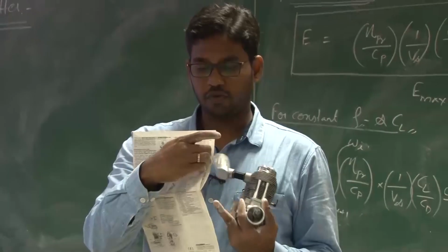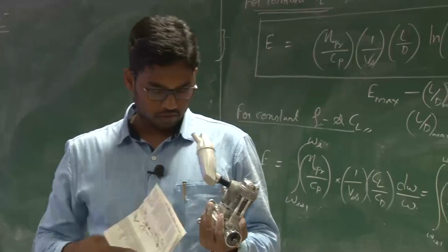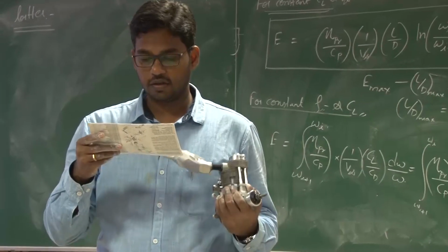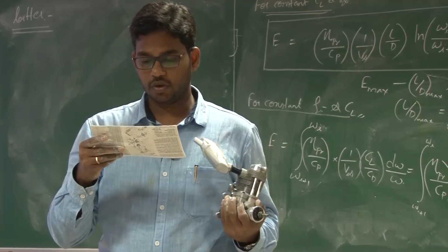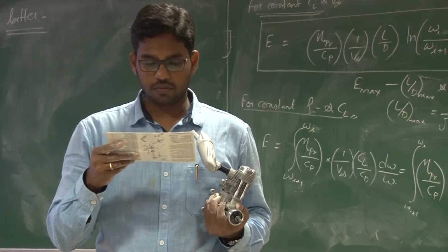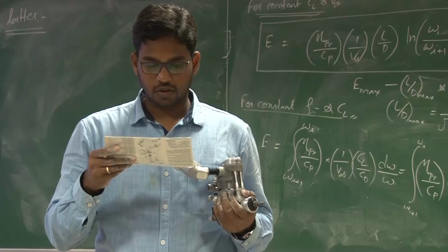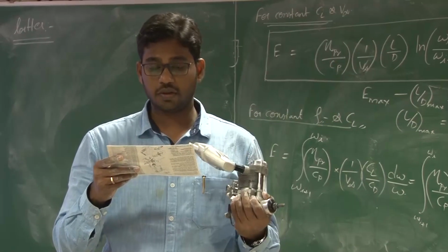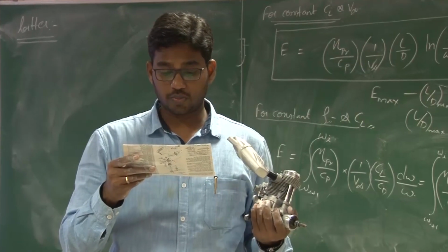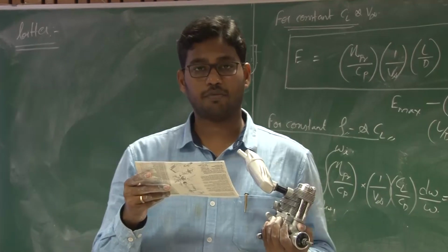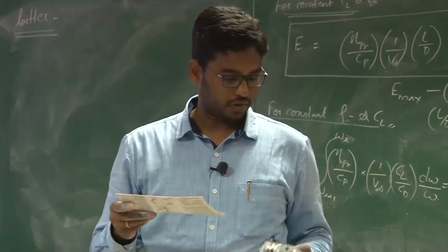It is a GF40 OS engine, with 39.96 cc displacement, a bore of 40 diameter, a stroke length of approximately 32, and a feasible RPM from 1800 to 9000. The output is 3.5 HP at 8600 RPM, and it weighs approximately 1.7 kgs.